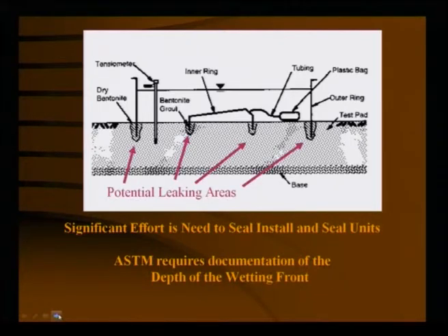You see, significant effort is needed to install and seal units. That means ASTM requires documentation of the depth of the wetting front. There might be a chance of leakage here, a potential leaking area, here may be leaking, here may be leaking, it has to be sealed by means of bentonite slurry.